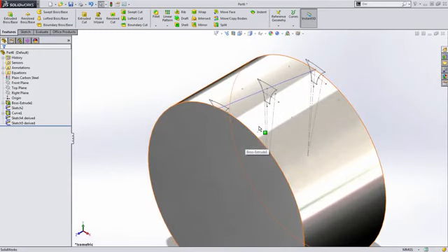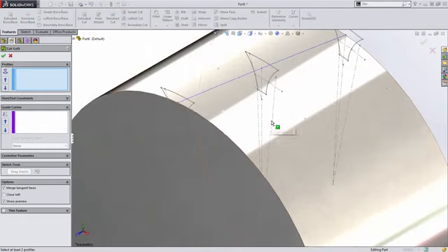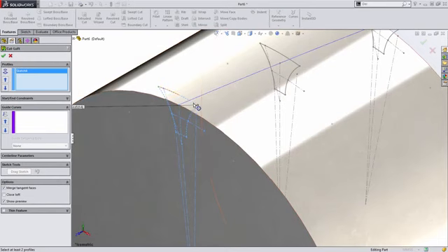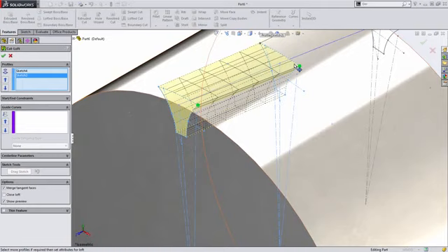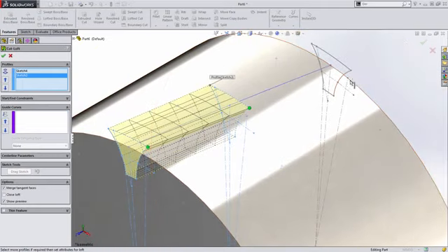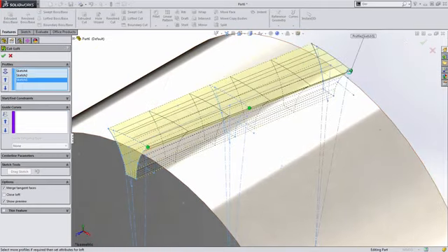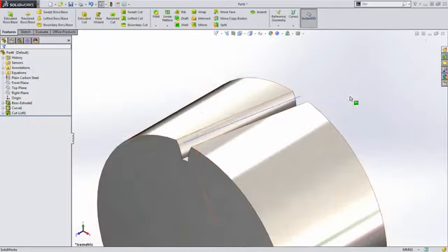At this point, all we need to do is create our lofted cut. To do this, we're going to simply select each profile. Now it's important to select the profile by the same area in the geometry. Let me explain. I chose this profile near the upper right hand corner. If I select near the opposite corner in the next profile, you can see we'll have a problem. Of course, Solidworks allows you to correct this with these drag handles easily. We then need to select the last profile and simply right mouse click to confirm.